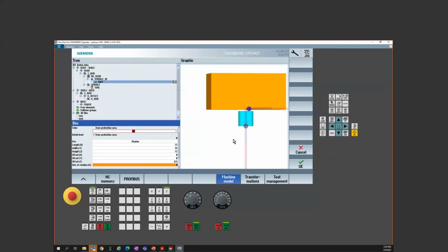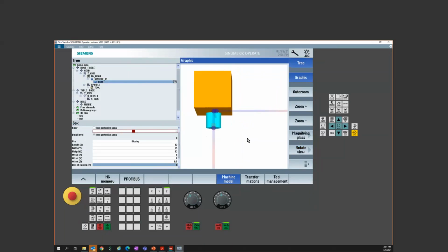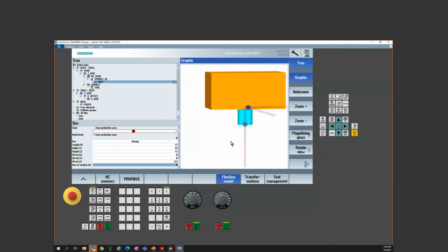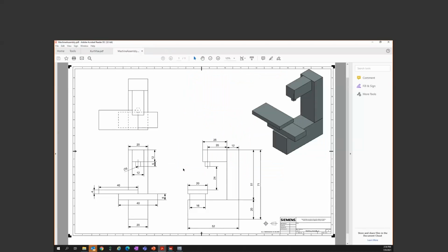Now, as far as the X offset, I don't need anything because my spindle would be dead center of my ram, but I'm going to need some positive offset in my head in my Y direction. So if you look at your little layout and I look at the side direction, I see the center line of the spindle from the back is 20, but from the middle of the object, well, I got 10, 10, right?